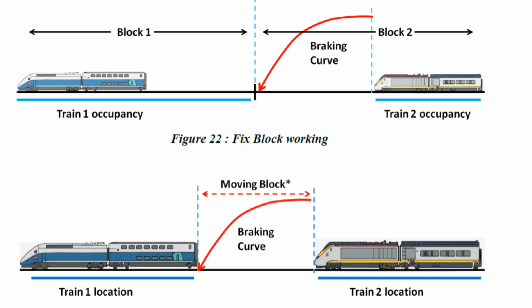Because of this lack of precision, the system has to assume the absolute worst-case scenario. It claims the entire physical block for that single train. Plus, these blocks are sized for a train traveling at maximum line speed, which requires this massive safety distance. This creates a tremendous amount of wasted space right behind the train. Train 2 literally cannot enter Block 2 until Train 1 completely clears that previous block. It's safe, sure, but it is highly inefficient.